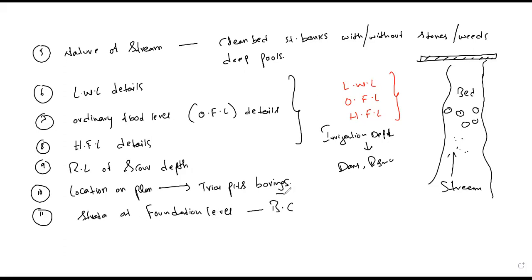What do you mean BC? Bearing capacity of that particular soil. So we need the bearing capacity of that particular soil at that particular foundation level. That information is also needed to design the bridges.